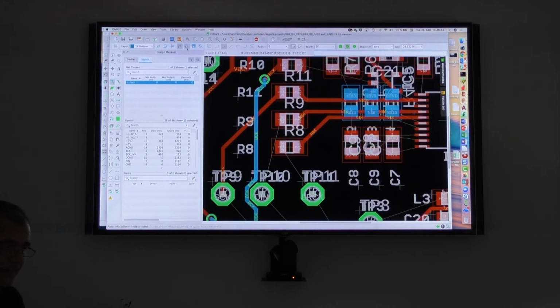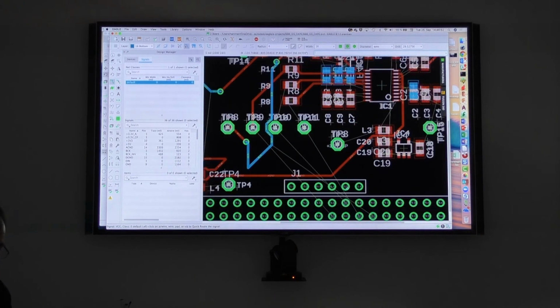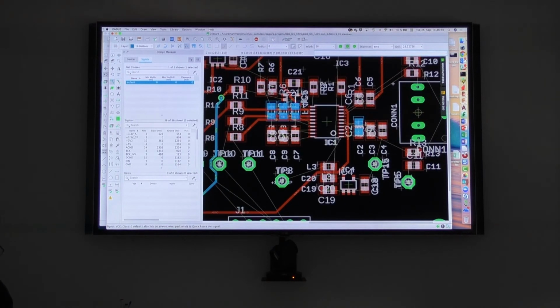You can say, click this, route one AirWire, or route the whole signal. This can also be done. If you have a more complex signal, like a ground signal, then it will go through that, but there is a limitation at the moment. It's not possible to have more than 16 or 20 air wires in the signal to have it done completely. But it helps, and you can also say I want to have several signals routed.